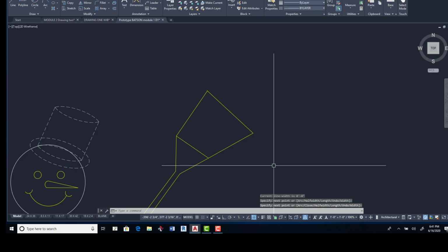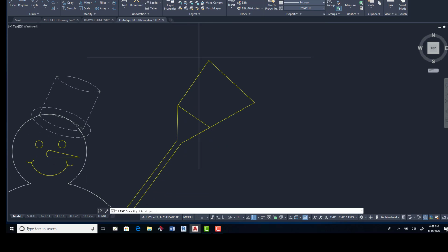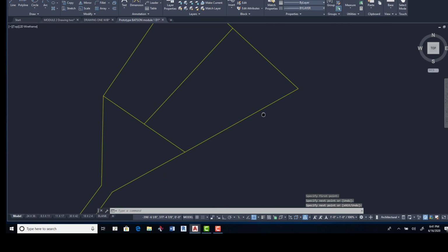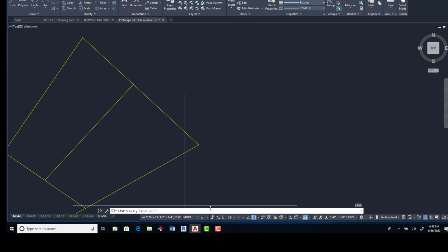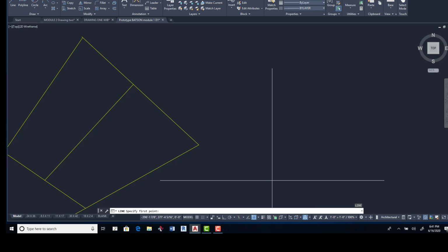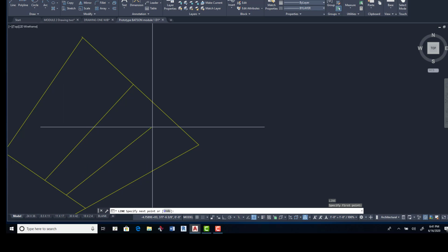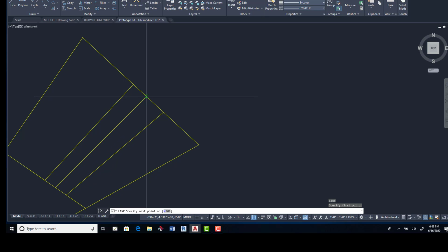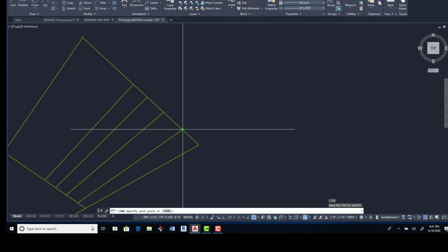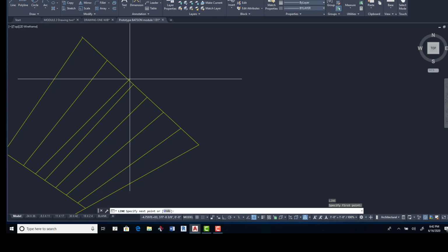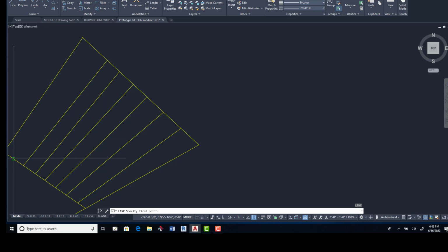And there you go. And then you can draw your line from the center to the center. Okay, now you need your nearest. So let's make sure nearest is on there. See nearest? Where's nearest? Click on nearest. There you go. Click away. That way, no matter where you select, nearest will be there. Select. There you go. Nearest. And I always go center, and then I go center. That way it helps me